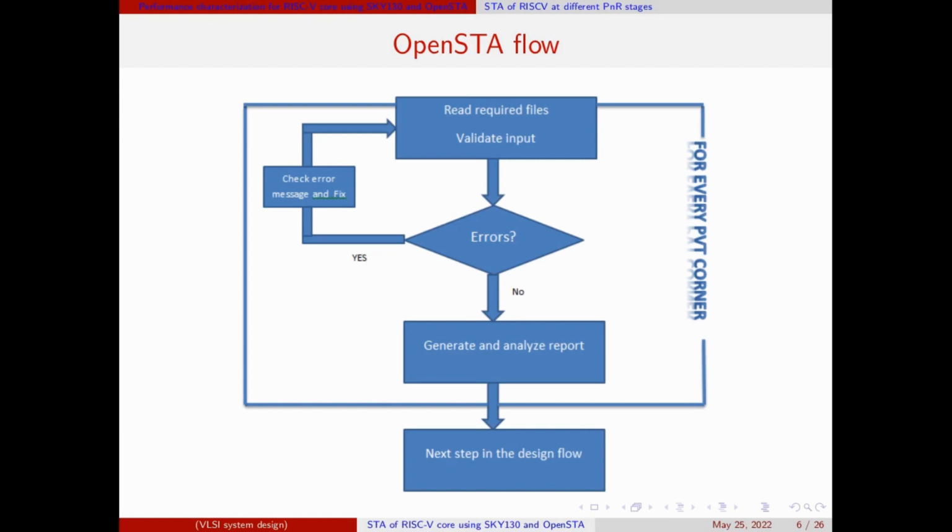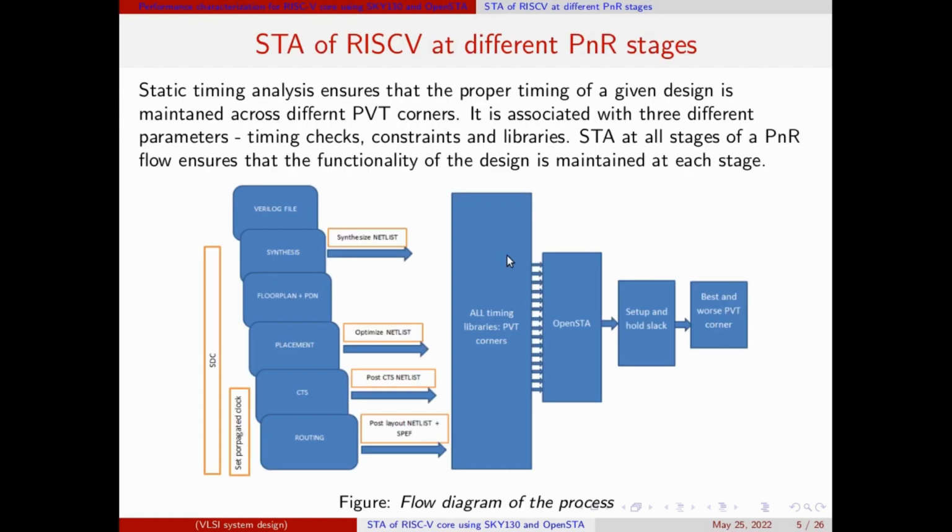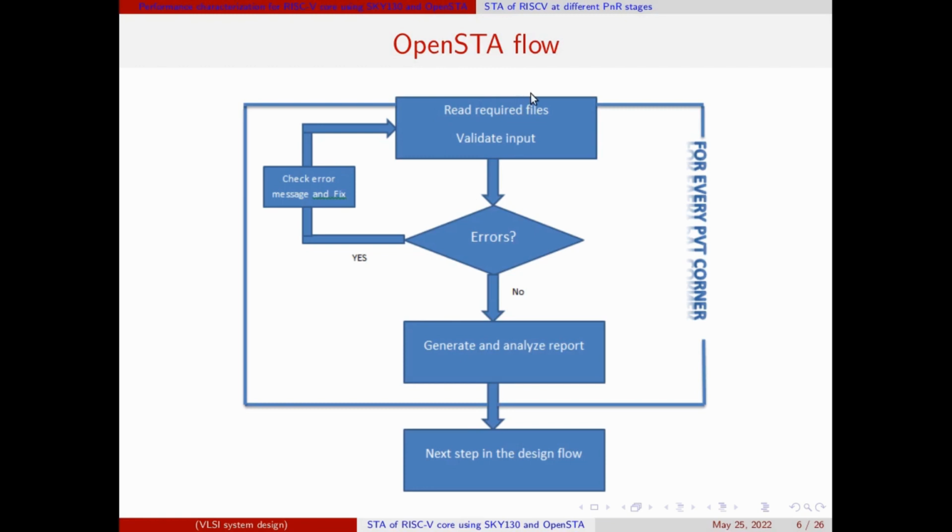The required files are the timing libraries, the netlist, the constraints, etc. We provide these files in the form of an input Tcl script to the OpenSTA tool.